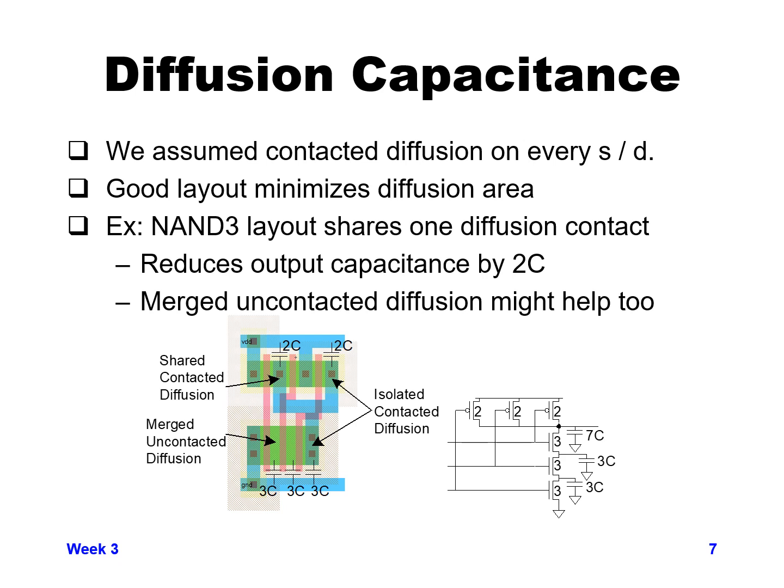One more thing we need to talk about relative to this topic is we've been assuming up until now that every gate is individually laid out, and so the diffusion capacitance that we're counting for each gate is the same every time we add a transistor. We're going to add the same amount of capacitance value. But in practice, we don't wind up laying things out like that. We try to minimize diffusion area wherever we can.